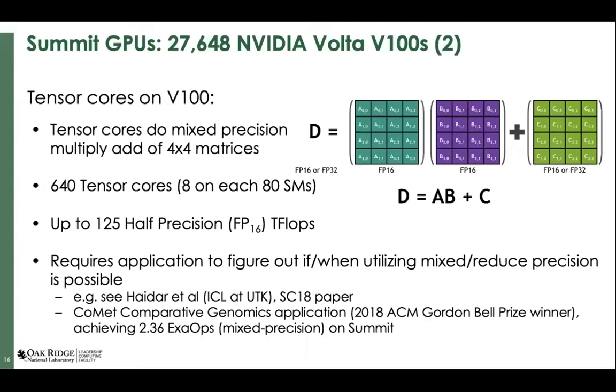The tensor cores basically allow for mixed precision calculations. And the Tesla V100 contains 640 such tensor cores, intended to enable faster training of larger neural networks. Each tensor core performs a matrix operation, for example like the one on the slide, D = AB + C with 4x4 matrices.